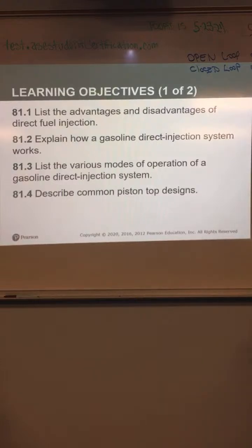Is that what the drive modes are, drive 1, 2, 3, 4, or the low and high? Oh, you mean your shift modes? No, that's just modes of operation, meaning what type of mode the fuel injection system is entering at certain times and operating conditions. Okay, and then it requires more calculations to be performed by the PCM. Parts are more expensive, there's more parts, and pistons are even different because of where the fuel is injected, okay?